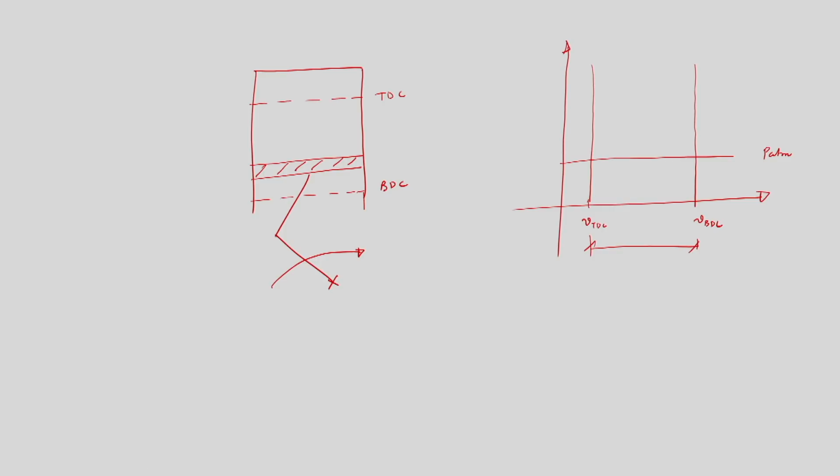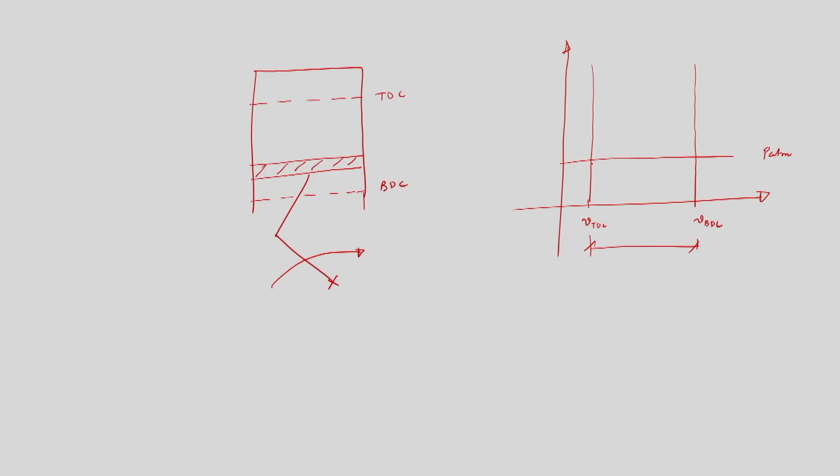Now when the piston is coming from TDC to BDC, we have a negative pressure inside the cylinder. So if I try to draw, the volume is increasing but the pressure will drop, the pressure inside the cylinder falls, and it will be like this. Again when the piston is coming from BDC to TDC, that means during the compression stroke, the pressure will increase and the volume will decrease. When the piston comes to TDC at the end of the compression stroke, pressure is high and volume is reduced.